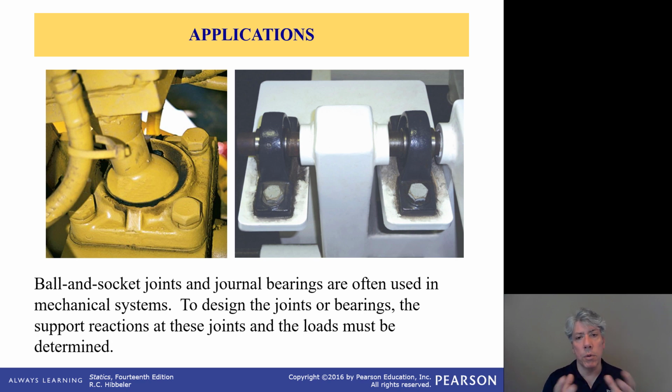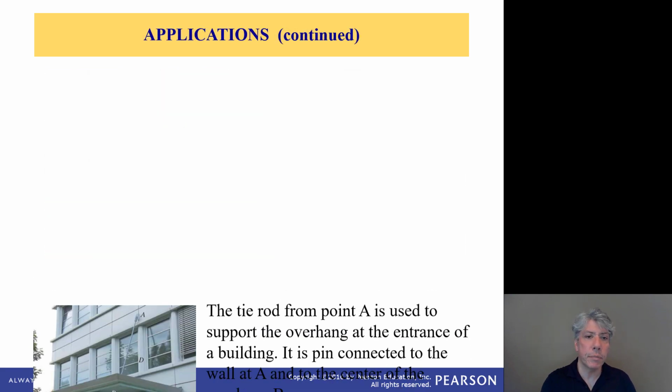So it's a little more valid to say that we don't assume that these bearings provide any moment support or any moment reaction to the shaft. We'll see that a little bit later. There's a whole table you'll need to mark in your book.